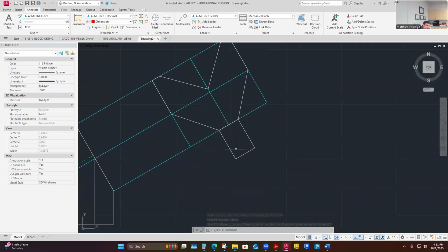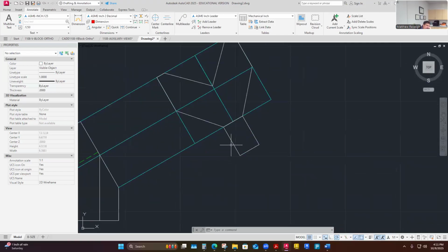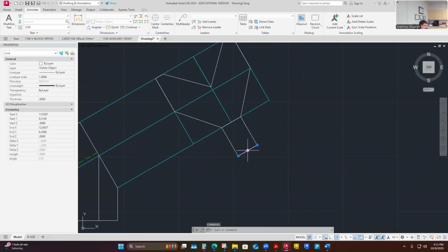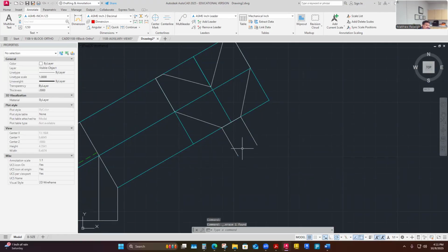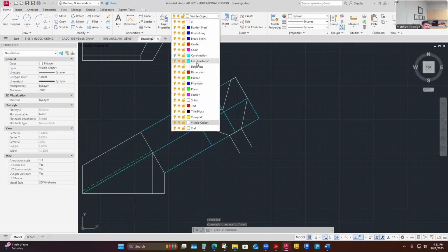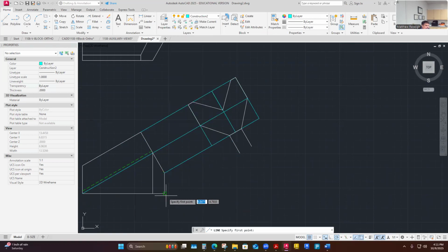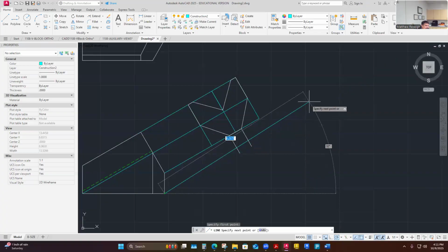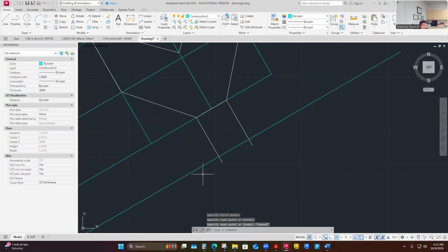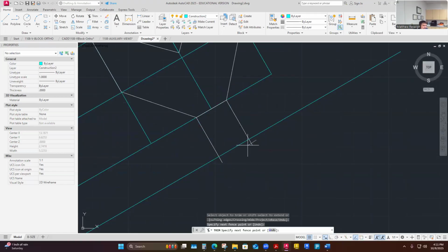Oh, I shouldn't do that. Sorry, I've kind of messed that up. That shouldn't be a full three quarter. Those lines coming down are good. That one is not correct because it's going to be foreshortened. So what I'm going to do is project this up. I'll show you where I made the mistake. This one needs to come up and across. I'm just drawing it way up and across. This shows where those would be foreshortened to. I'll trim them like that.